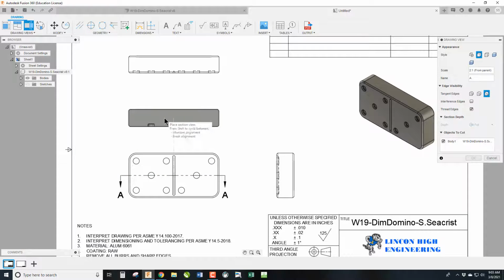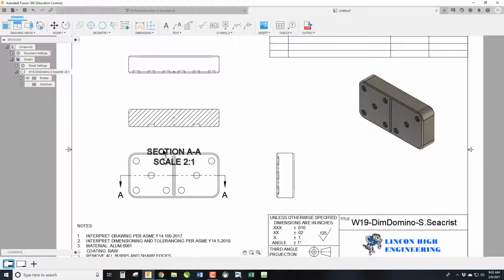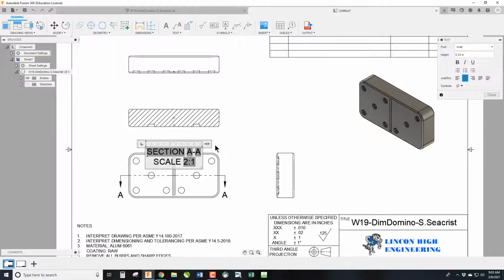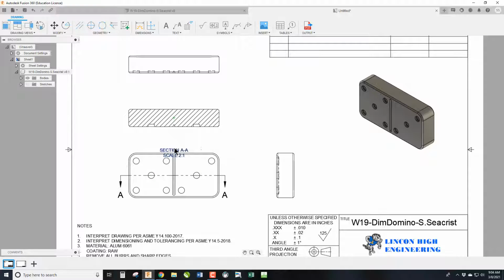And then I can roll up this section view, and you'll notice that it has the section view lines. It clearly shows you the whole shape as well as that V. Even though it's small, it shows us that V. So first off, this is way too big. Let's highlight everything and make it 1/8 scale, so 1.25 size. And then we can drag this up here to denote that, hey, that section view is that size. This also denotes where it is.